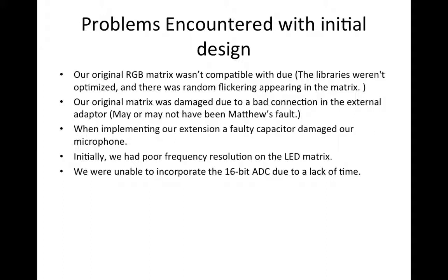When programming the matrix, it was found that it offered poor frequency resolution when music was played through it. This was because while human ears can hear from 20 Hz to 20 kHz, we cannot distinguish evenly between the whole range of frequencies. We actually have a lot higher resolution between 200 Hz and 2 kHz, which is the range that most music occupies. To fix this, we increased the number of samples and then averaged them out over a non-linear range of frequencies, approximately logarithmic. There was a greater resolution in the 200 Hz to 2 kHz range after this, which improved results markedly.